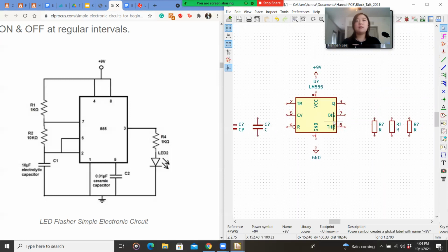And so now what we want to do is actually connect the dots, essentially. In order to lay out the connections that this schematic had, navigate to this right taskbar again and click place wire. Whenever you're placing a wire, you want to go from dot to dot, but you don't actually have to do it directly, in the sense that you can shape the wire to be what you want it to be.